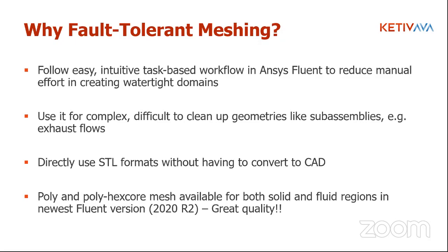You can directly use tessellated scan data without having to convert it into solid CAD formats and generate a fault-tolerant mesh. And lastly, with the newer updates in Fluent, both poly and polyhex4 mesh types are available for you to explore and use and generate a great quality mesh.